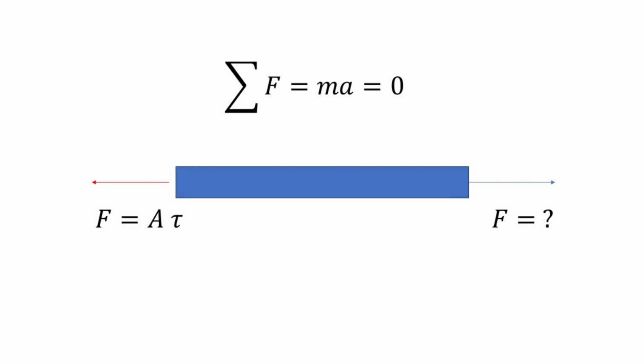Back to the moving plate in this problem, there are only two forces along the direction of its movement. One is the applied external force that is unknown. The other is the drag force as a result of the fluid's shear stress. And as we discussed before, the shear stress is linked to the viscosity by the velocity gradient. Now the solution process is clear.